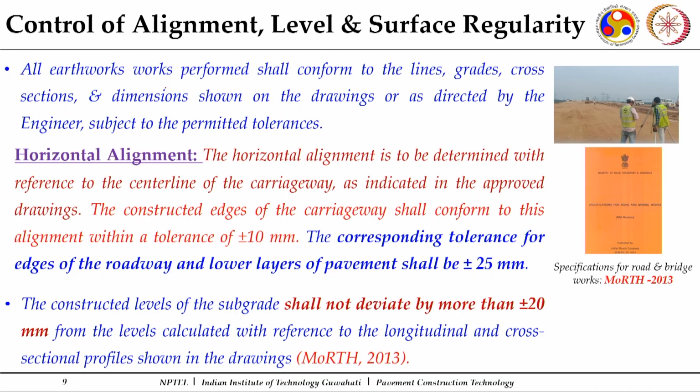So, all earthworks performed shall conform to the lines, grades, cross sections and dimensions shown on the drawing, because the width of these layers will be different. As I mentioned in the earlier lecture, when we construct drainage layers, they are to be exposed to the ends, so they are constructed for the entire width. So, that needs to be ensured.